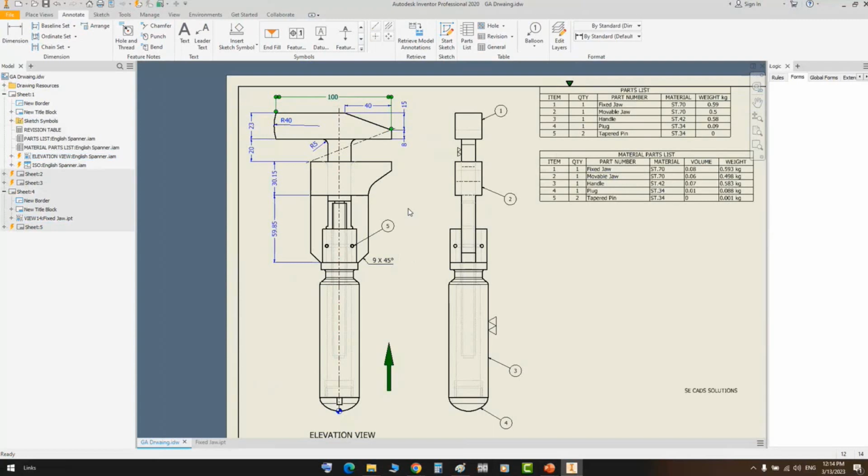So here's the power of 3D CAD software: any update on the 3D model will be reflected automatically, including on the properties of this part, like the weight. The weight will increase because the volume of this part increased. So from the volume and the density, you will get a new weight instead of the old weight, based on the change in the dimensions of this part.